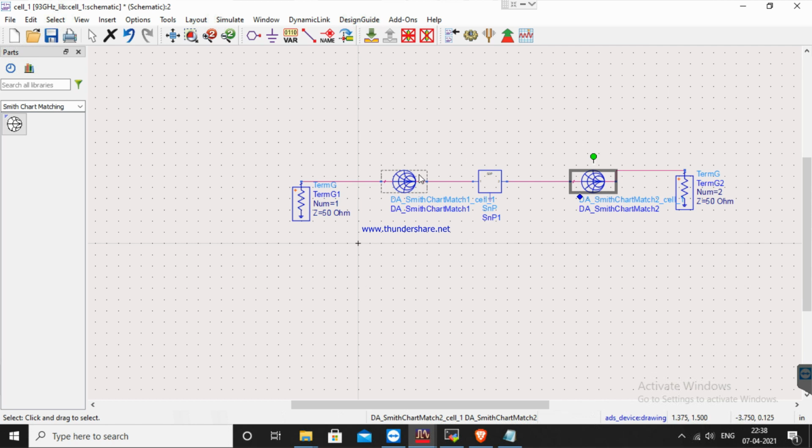and you can see how without touching the Smith chart, like paper Smith chart, we are able to do it here, and without calculation also, those big formulas, those using MATLAB or calculator, nothing we need to do. So after that, how to simulate this example? To simulate your example we need a simulation controller. So we will do S parameter simulation.